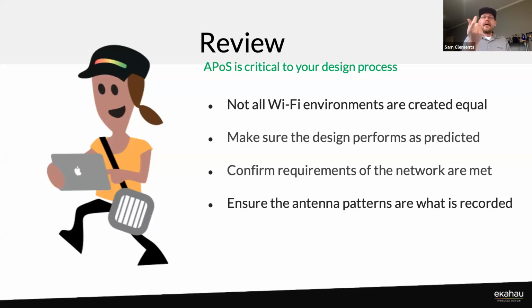Take that measured data and put it back into your predictive design to make sure that your next one is going to get a lot closer to what you think it should look like predictively, so that when you place that AP and walk around it, you're not wasting an hour. Nobody wants to place an AP on a stick and walk around it and go, oh, it's in the wrong location, pull it down, and then go spend another hour for that AP.